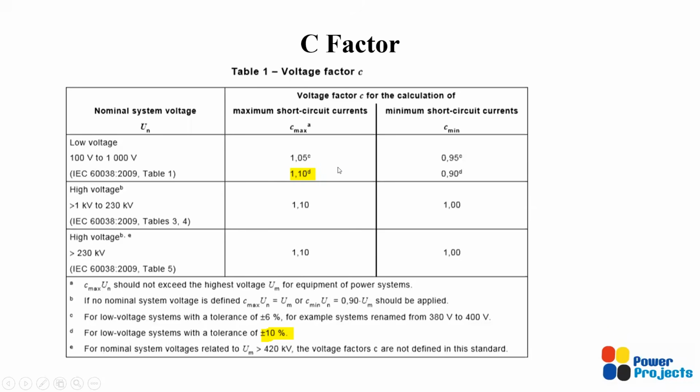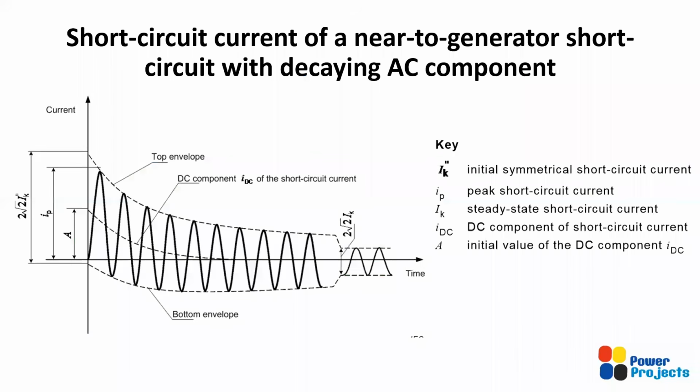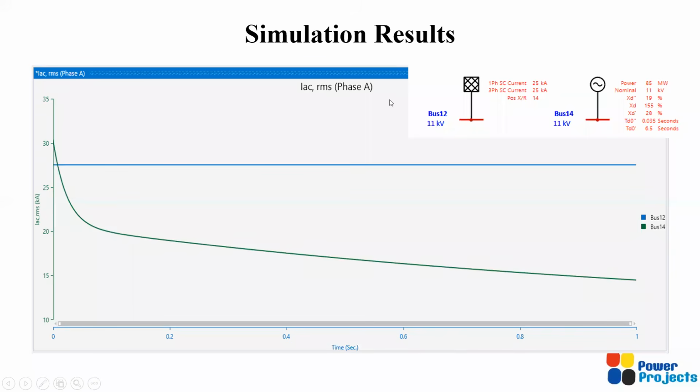The C factor comes in the numerator, and it is directly multiplying the current. So probably that's also in the previous slides somewhere. If you have looked at it, with a 1.1 C factor, the current is probably, though I have given 25 kiloamps, so probably this occurs at 25 kiloamps. Here you can see this 25 into 1.1, 27.5, it's because of the C factor.